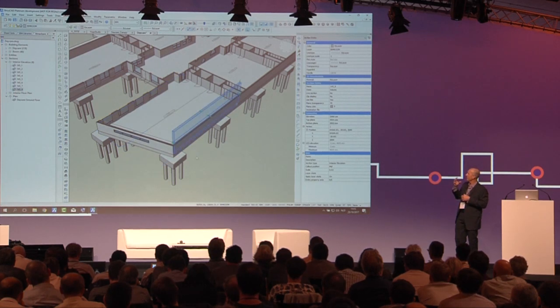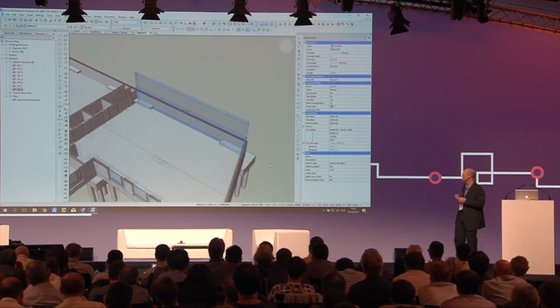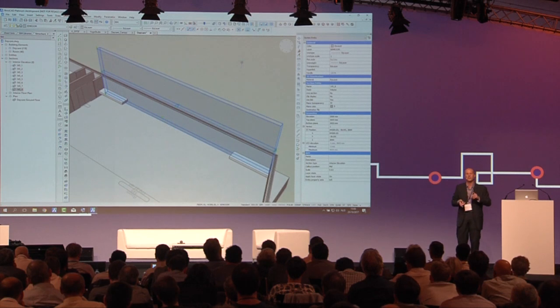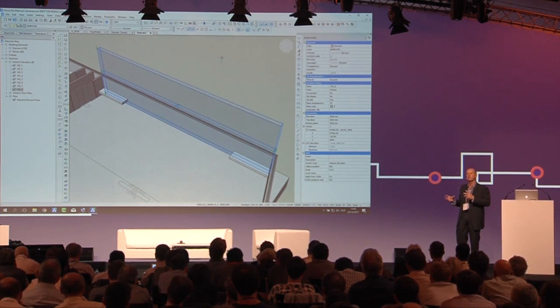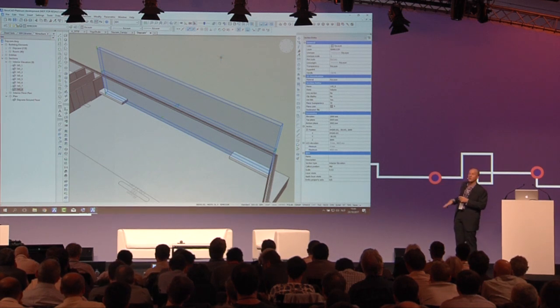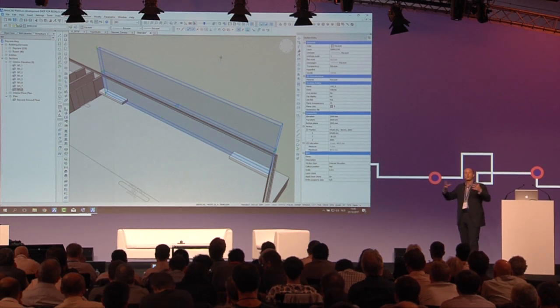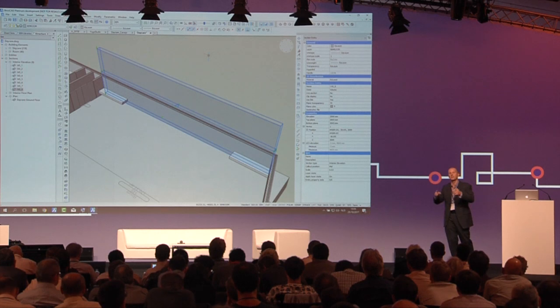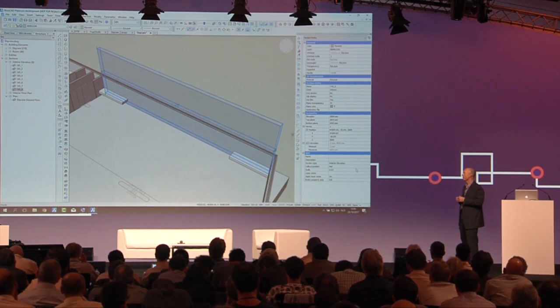Now, if we select one of the interior elevations, they're being laid out with a default scale. There's a link across all of these so that they go to the same sheet. So you don't have to worry about any of the properties there being adjusted unless you wanted to. And with other BIM sections you create, you typically have to put a destination file to point them to the same place, but BricsCAD BIM is already doing that for you.